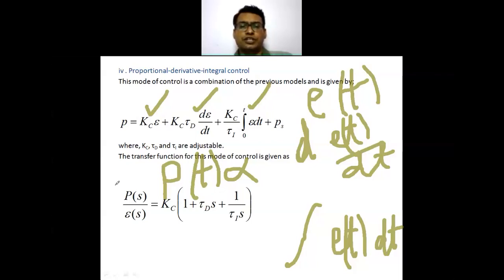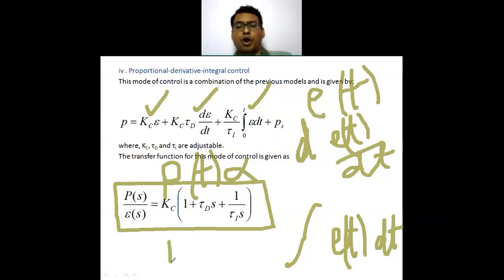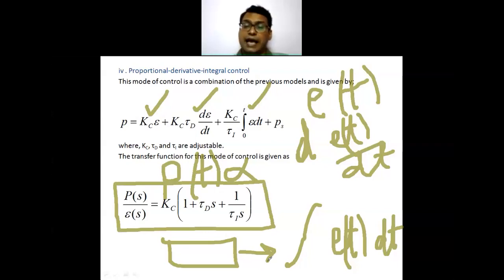So your transfer function, that is the output deviation variable upon the input deviation variable, that is the P is your output. Output is your pressure, nothing but the pressure from the controller, or the current or voltage from the controller in case of an electronic controller. In a pneumatic controller, the output is directly a pressure going to the control valve. However, in the electronic controllers, we are providing the I to P converters, so that the I is your current and P is your pressure.